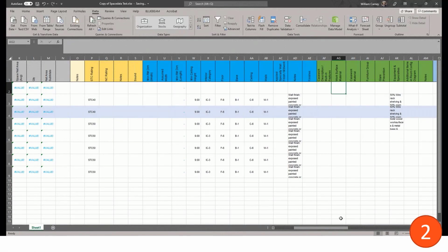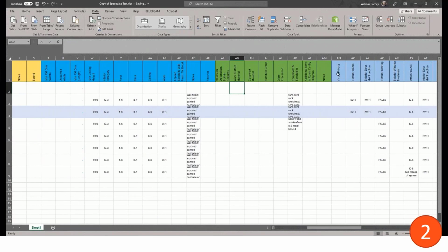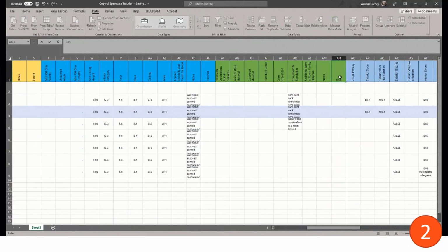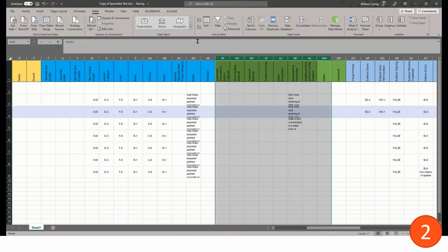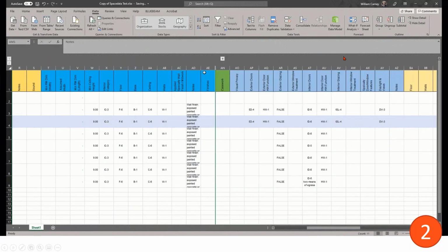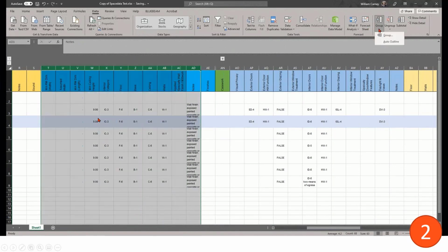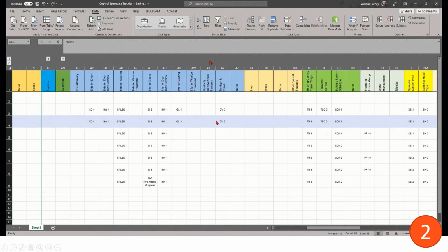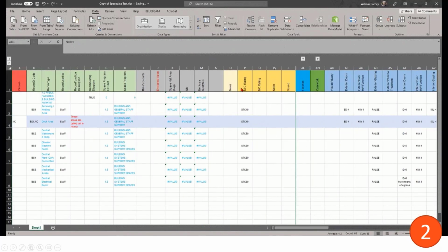That lets you hide and expand the columns of information and focus where you need to, because it really is a daunting amount of information when you're not editing it right in what's really a deliverable, the room data sheet. So here I just select them, you hit group, and then that can expand and contract, which does make this actually usable. And then you just don't map that text column for finishes, but you map all the other columns to your space programming custom parameters.